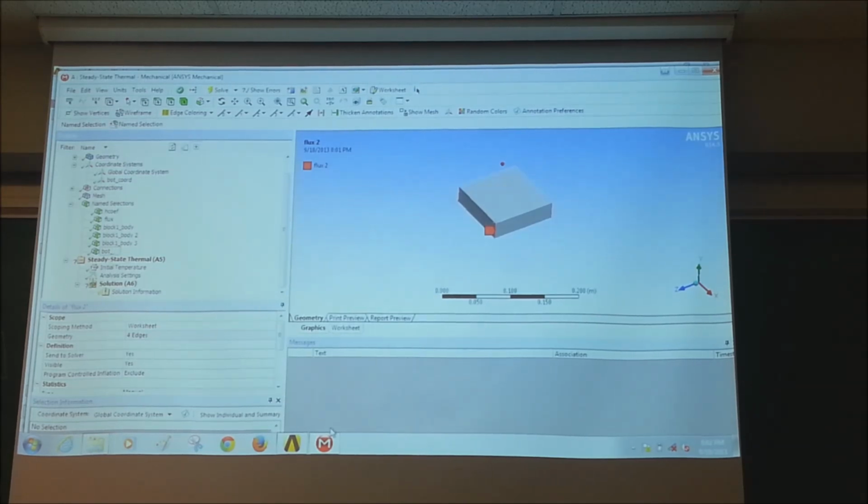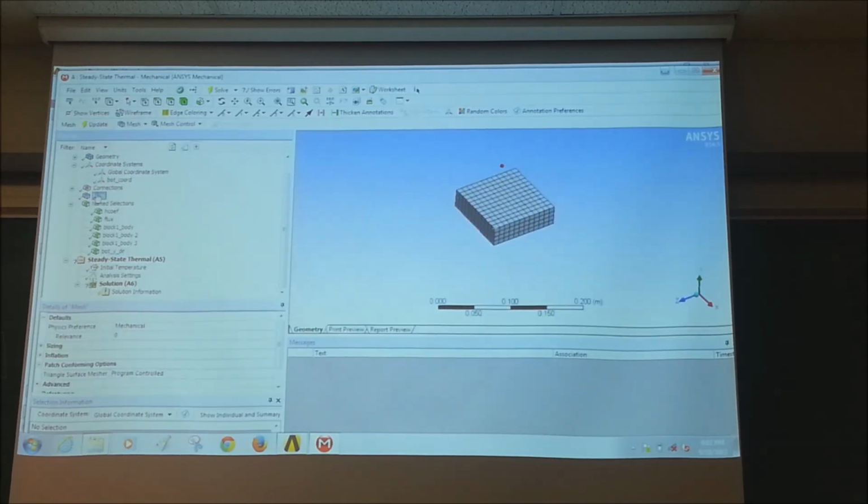Y direction, right? All right. Just keep that in mind. I'll use that in a minute. So I now got this thing called bottom Y direction. So what I can now do is, when I create a sweep, if it's sweepable, you can go up here to meshing, check to see if show sweepable bodies, and it's certainly sweepable.